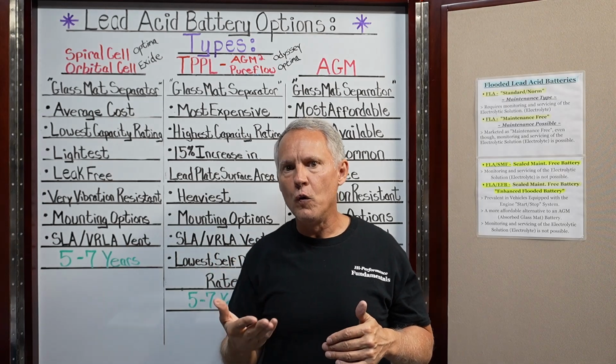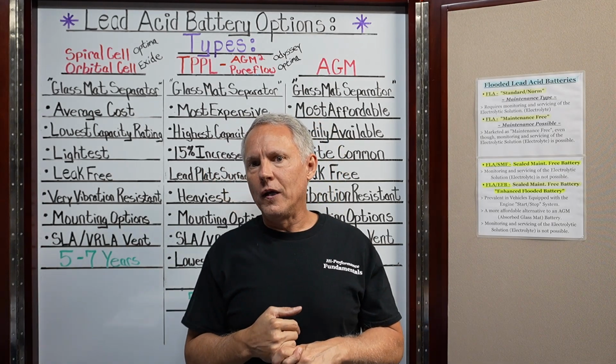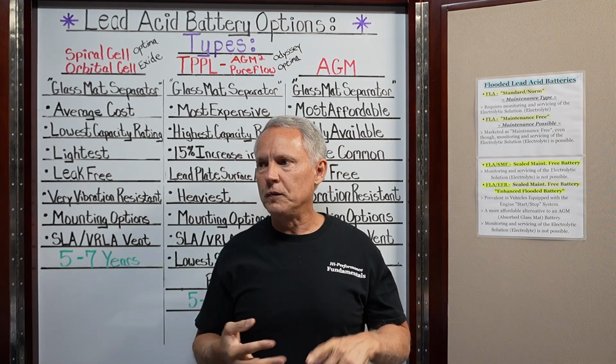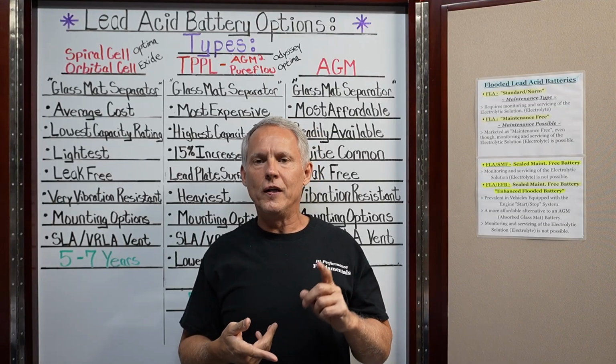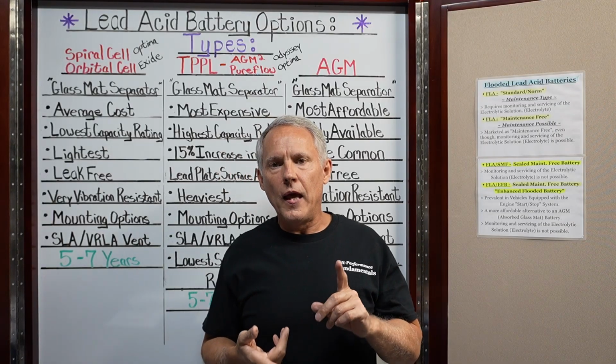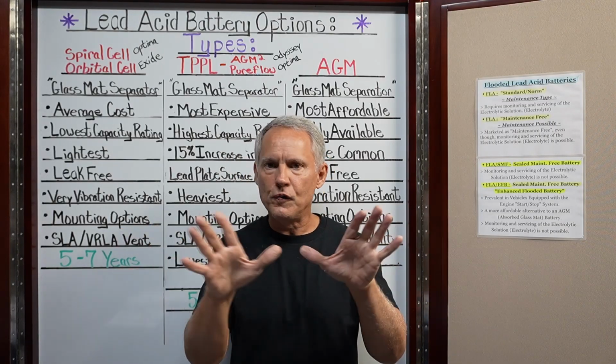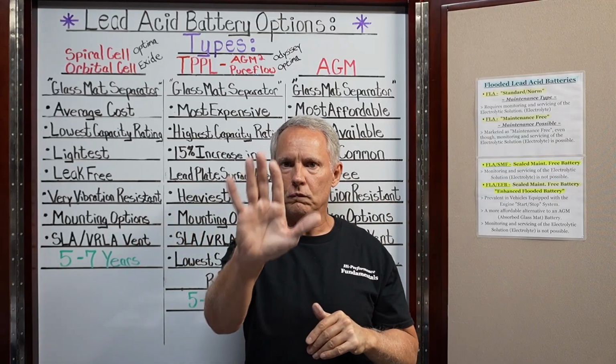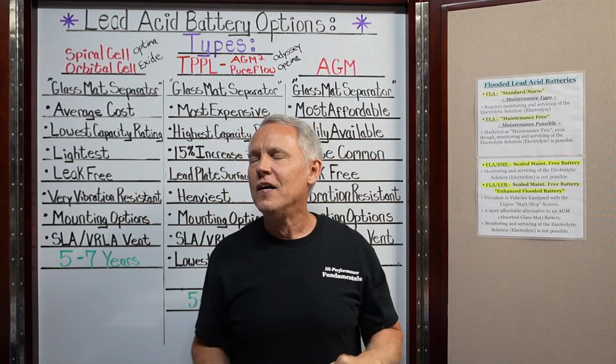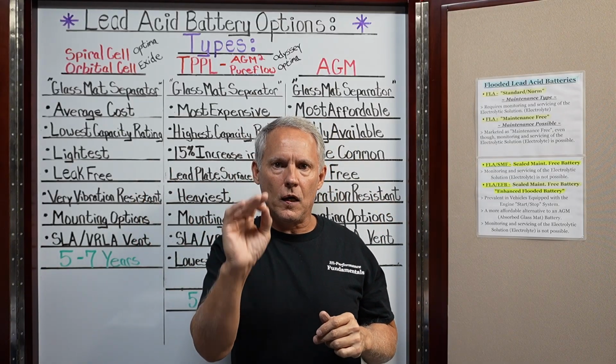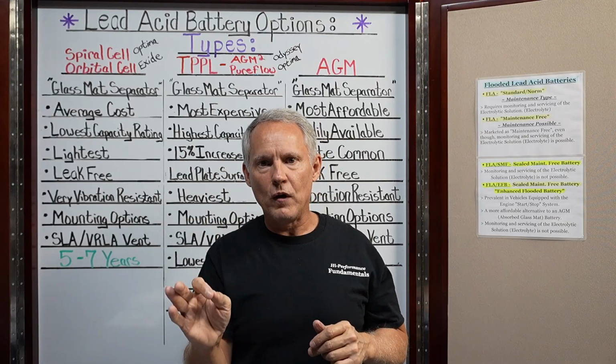Okay, now what you have to know is that a lot of your onboard electronic systems, your computer control systems, your fuel injector drivers, your ignition coil drivers, they have a safety, and they're not all the same. And believe me, they're not all the same. So don't get carried away, don't get crazy. But they can cut off when they reach the 18 volts threshold.